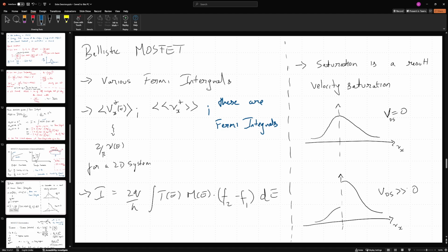Apologies once again. And then we have a ballistic MOSFET, wherein again the same concepts can be carried over, but we understood that the physicality of the system is significantly different. So once again, to repeat, in a ballistic MOSFET, the gate controls the energy levels that are present in the channel. I will also write it once over here.